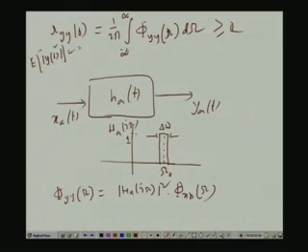Now, in this case, what is R_yy(0)? I have to integrate Φ_yy(ω) from minus infinity to infinity, but there is no point in integrating over all frequencies, because it is 0 everywhere, because the input power spectral density, whatever it is, is multiplied by this narrow band pass filter. So the output power spectral density will be confined only around ω0, within this band of Δω; elsewhere it will be 0, because the magnitude of H_a(jω) is 0. You can even call it with the magnitude.